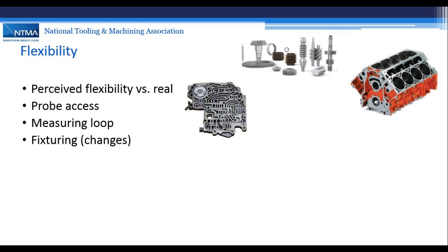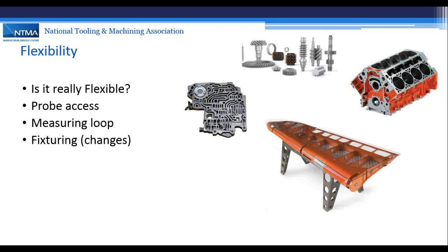So when there's change, we can easily change the fixture and make a programming change, and the flexible system has its payback. Whereas a dedicated hard fixturing system, if there's an engineering change, then it becomes more costly, more time consuming, longer lead time, when we look at fixture changing on those typical parts, and especially if those surfaces are on larger components, larger wingspans on aircraft or aerospace, or large agricultural type components or castings.